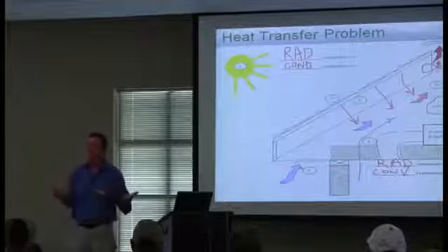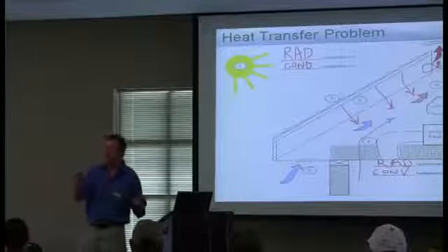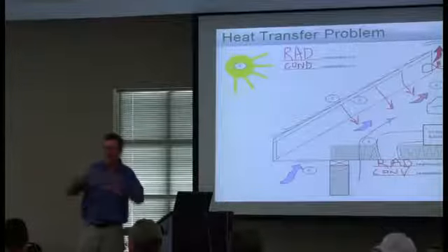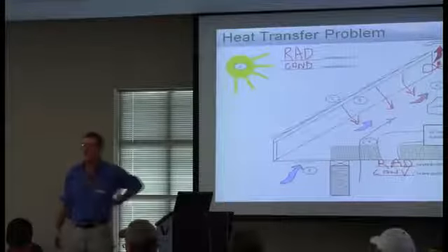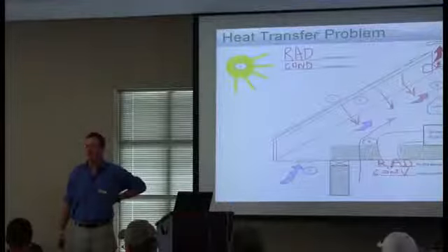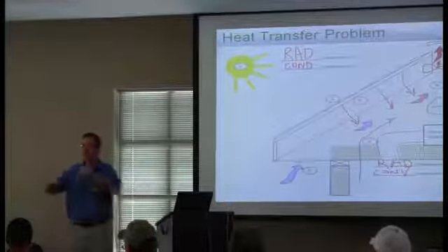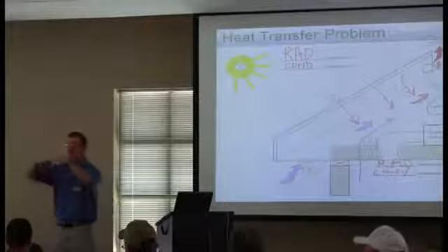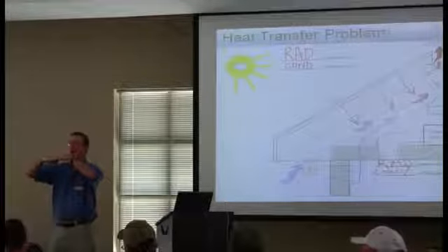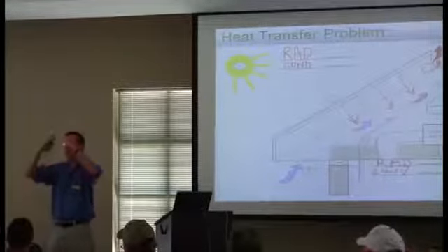And here's another bonus. Maybe this is what you're going to ask. So then that changes my load calculation on the Manual J? It does change your load calculation, because that space becomes part of the envelope. That is correct. But believe it or not, it can help your load calculation. You might think, because it has nothing to do with volume, it has everything to do with surfaces, though.